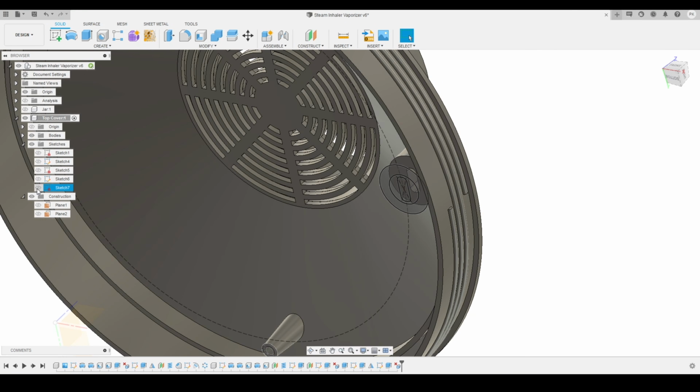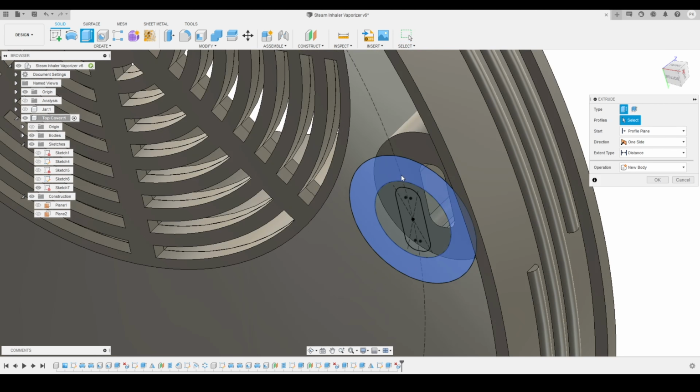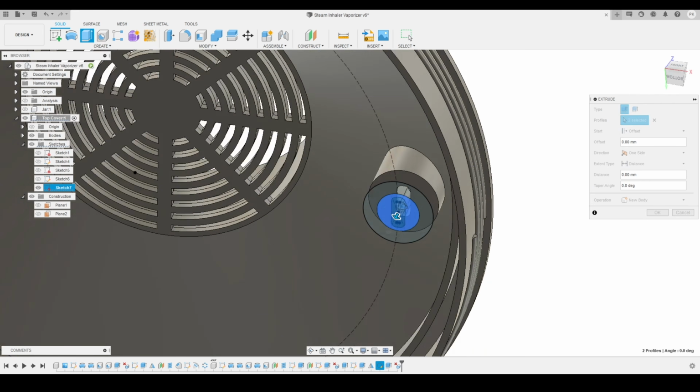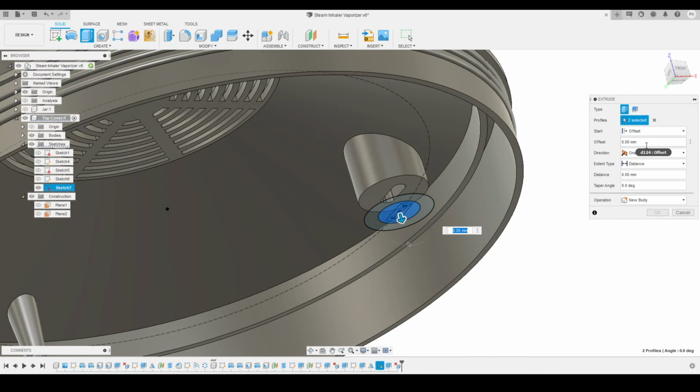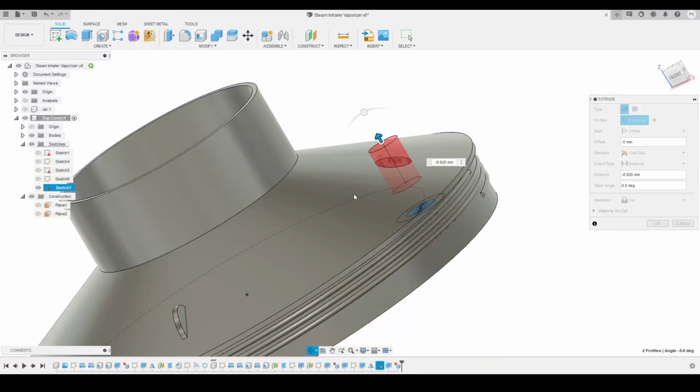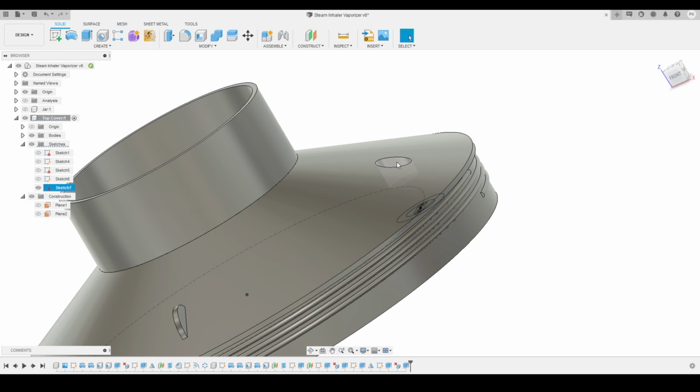Now I'm going to turn on the sketch again, and we'll select this particular profile and this complete profile, and I'm going to offset it again by maybe -5 millimeter like we did earlier, and then we'll make a cut like this. Here you can see we are making a through cut. So this is the kind of shape we are getting. Instead of -5, we can just increase that to -6, and then we'll press OK to set the results.